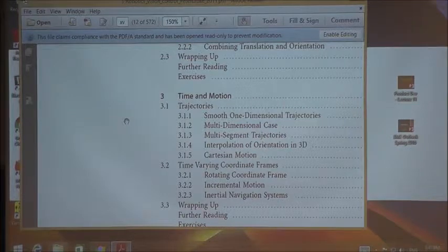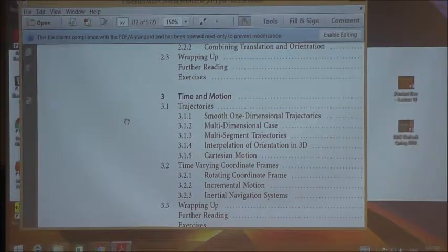And what are Denavit-Hartenberg transformations? What do those four parameters mean? Okay, and how do you transform from one coordinate to another coordinate in the process of having two translational and two rotational movements? Remember that? There are four parameters of DH, or Denavit-Hartenberg, parameters. Two of them were angles and two of them were distances.